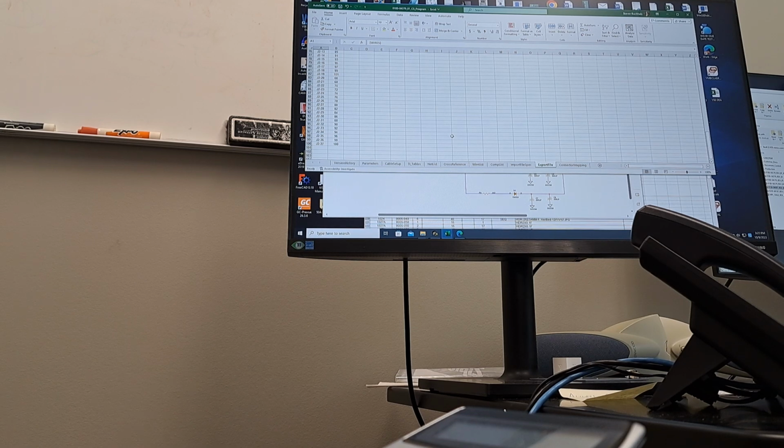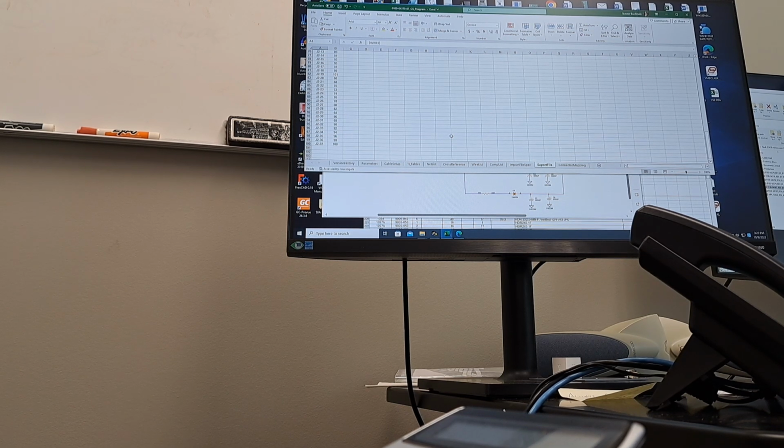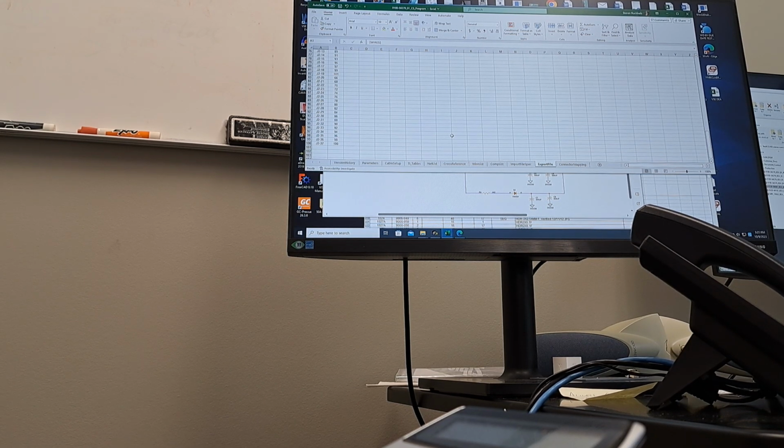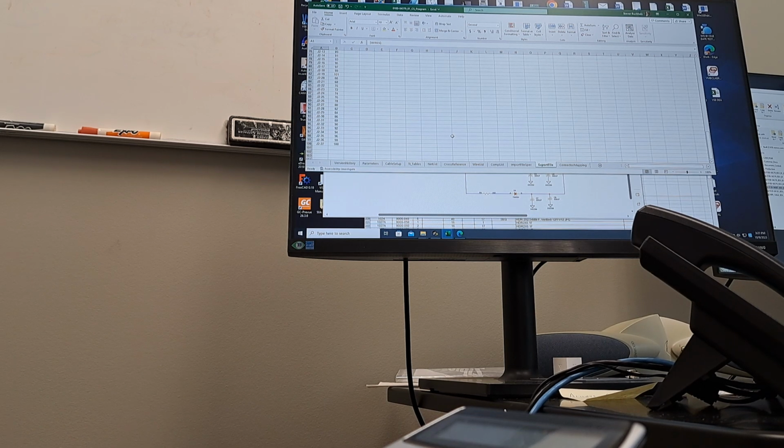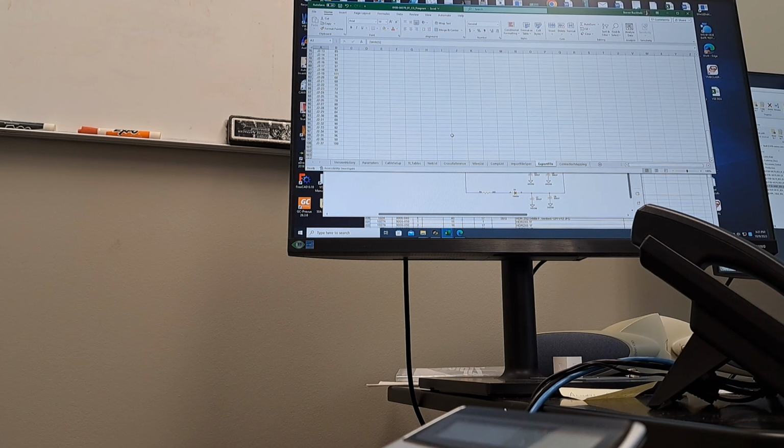So the cable scan system has thousands of points, and they start off on a board in that big cable scan box, and it goes to these 64-pin cables, and then from the 64-pin cable to an adapter to an interface on the board. When you see some of these adapters, you can see they're kind of kludgy. People have done weird stuff to try and fix them. Mass terminator ribbon cables will pull loose and things like that.